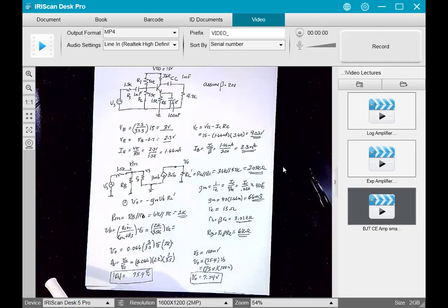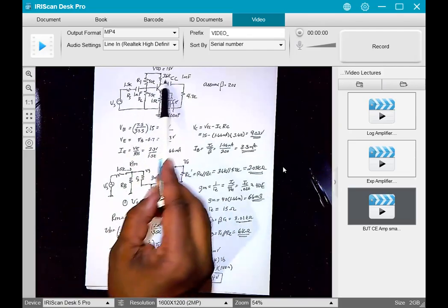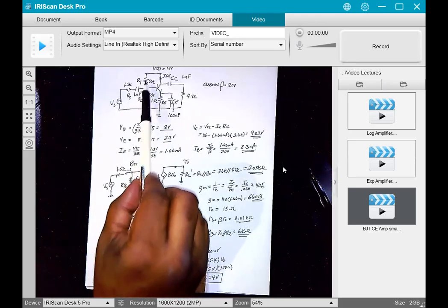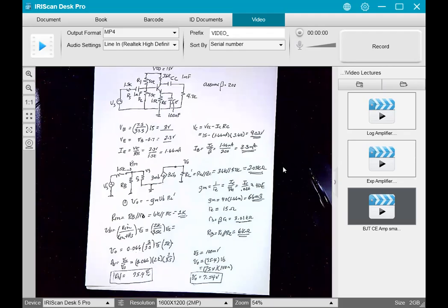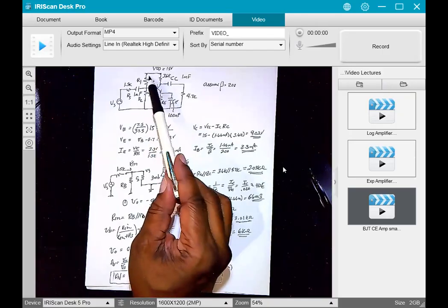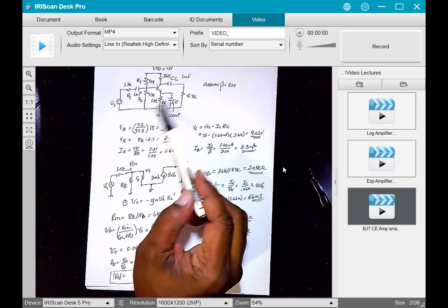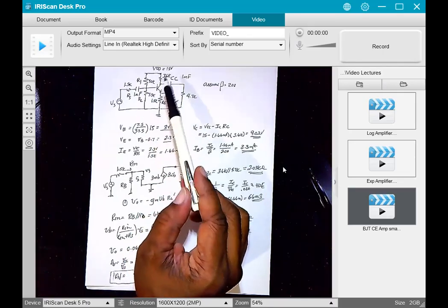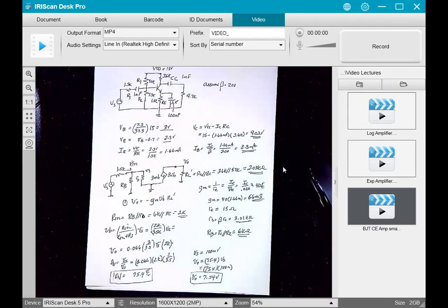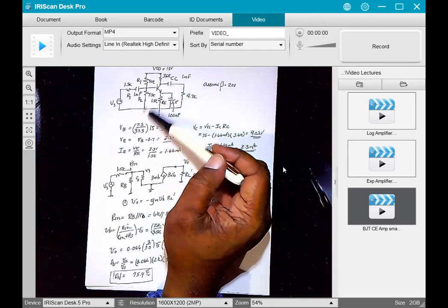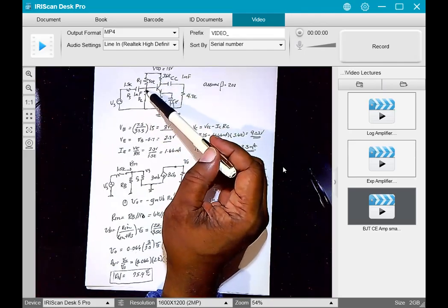If you look through the book, when you see this BJT amplifier, you'll see these values are not the same for every circuit they show you. They're different values. One of the things these do: if I make these resistors bigger, I reduce the overall current consumption in this circuit, because there's current flowing through here that's not really being used other than to set this voltage level.